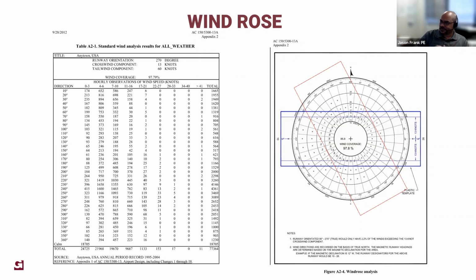In this case, this is basically as true north and south goes. It goes from 90 to 270. So that's based on true north wind direction. Now, when we actually number the runways, that is based on your magnetic north. So even though in this case you can look at the compass there and it says 90 degrees and 270 degrees, that would be a 9/27 runway. But because of the location of the airport, it might be a 10/28 as shown in the example.